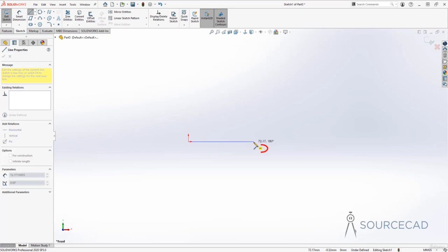Another thing is this yellow box with this line icon. Now that's a constraint. So in this case, it is applying the horizontal constraint on this line, which means if I make this line now, if I click here, I'll end up with a line that will remain horizontal, because as soon as I clicked, now you can see that we have that horizontal constraint added right here. Not only that, we also have a new constraint called coincident. Now that constraint will keep this line connected at the origin. So since we started with the origin, SolidWorks will ensure that it remains connected at that point.